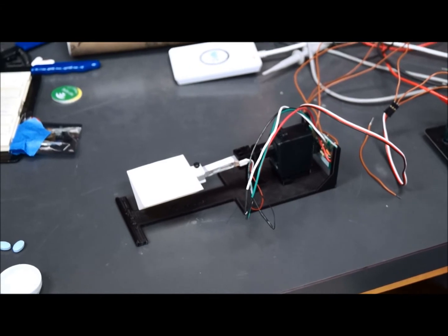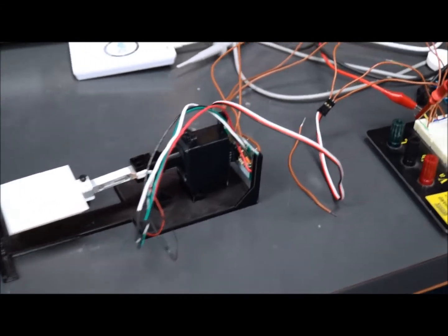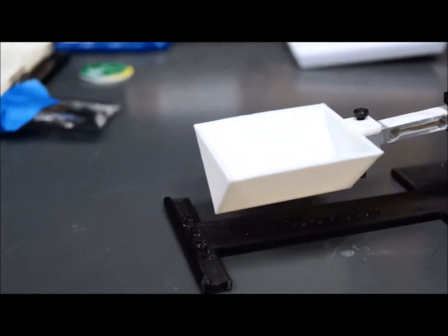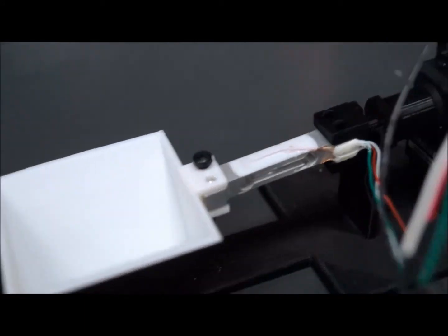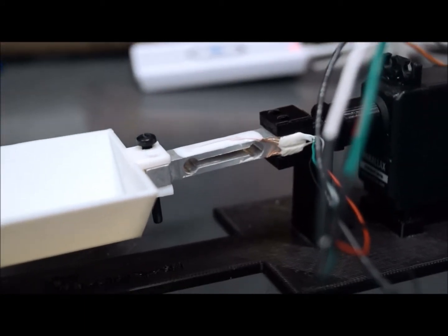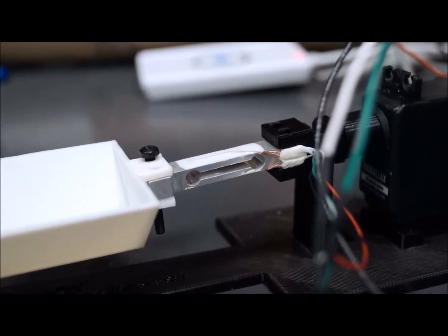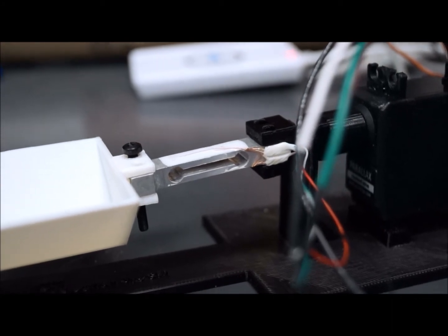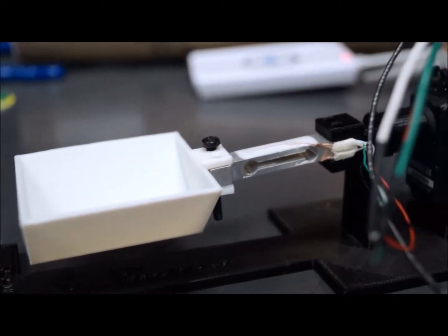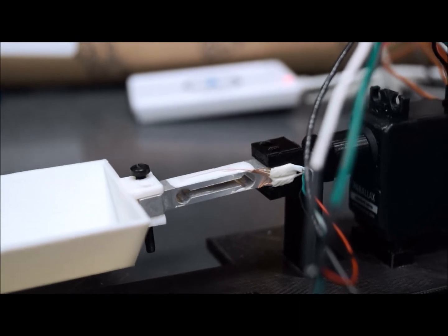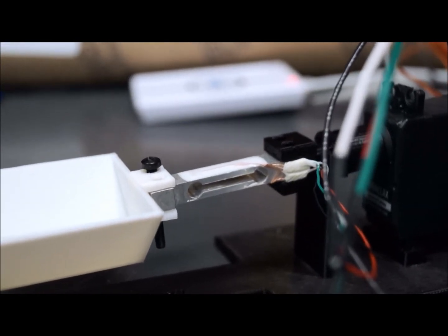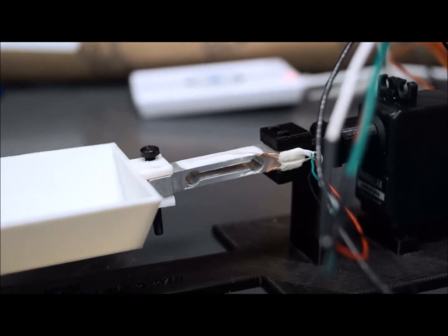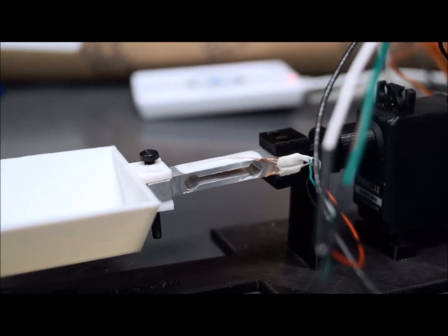This is a demonstration of the scale unit for our dispenser system. It's composed of a couple of parts. The first part is the pill trough, which will catch all the pills as they fall down from the upper compartments. The middle part is a load cell. This converts the amount of flexing it feels from the weight of the pills into a very small voltage. From our observation, a Tylenol pill will create a difference in voltage of about 5 to 10 microvolts per pill.